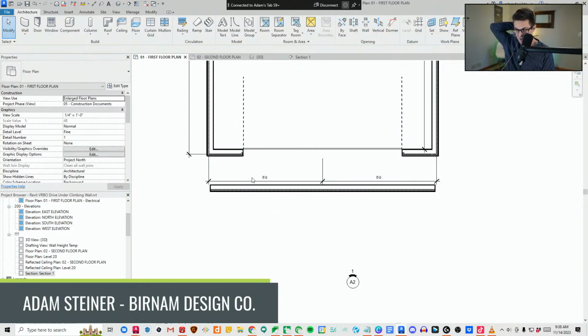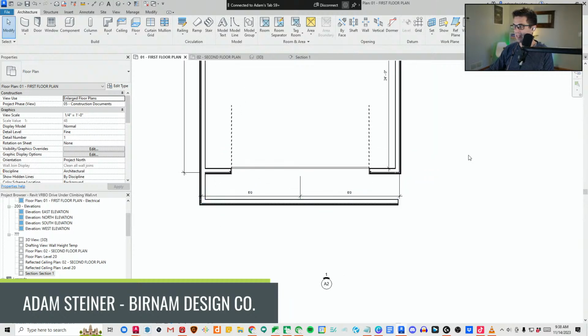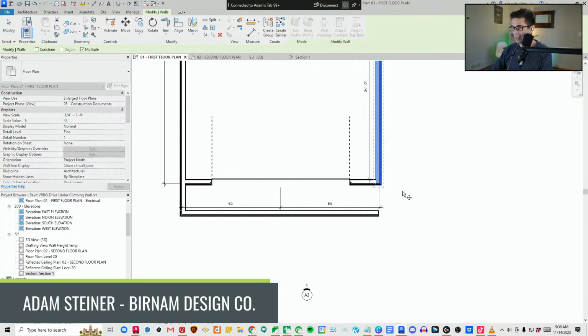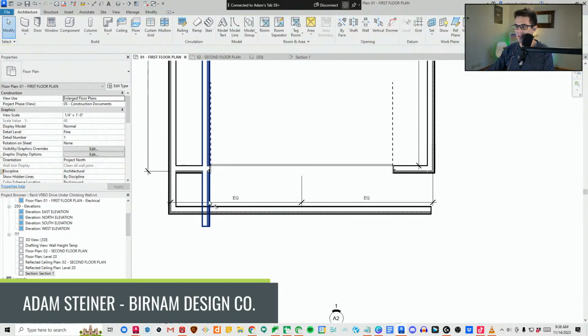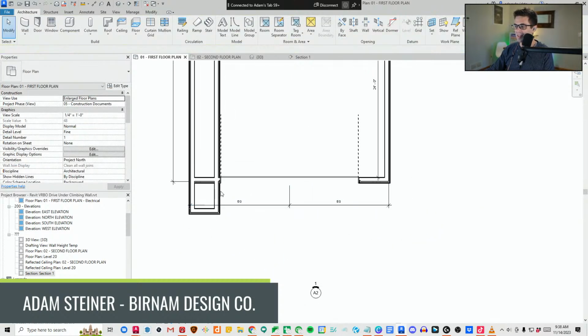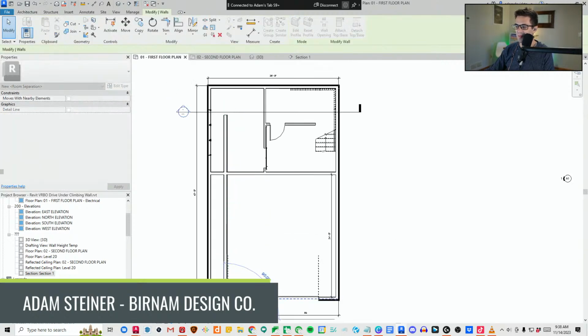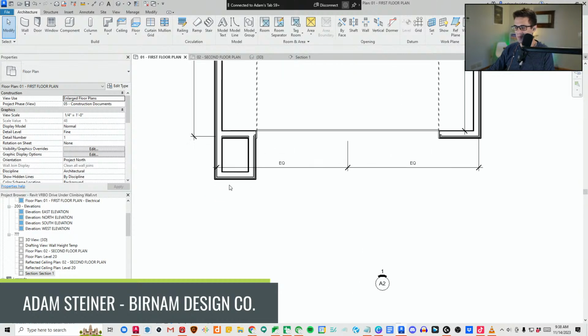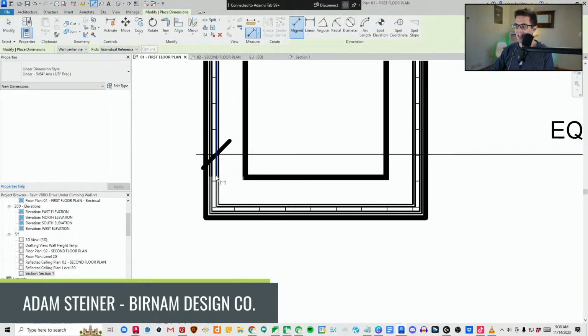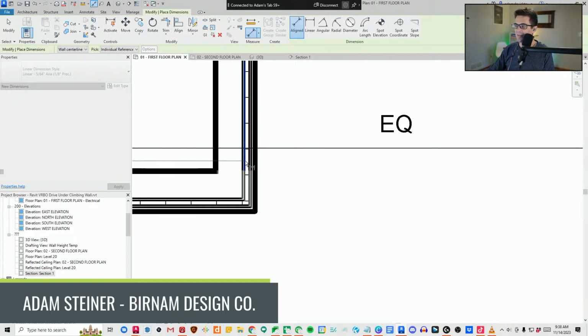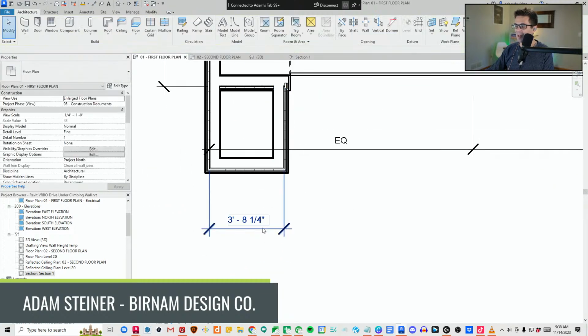I work in AutoCAD all day, most days. And AutoCAD defaults to inches as the base measurement, whereas Revit defaults to feet. So a lot of times I will mean to bump something out 48 inches and it goes 48 feet and it's completely outside my view range.